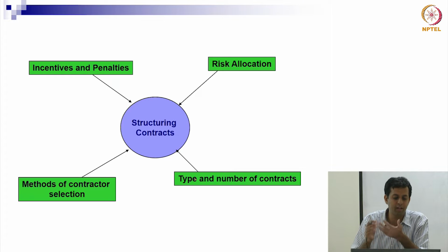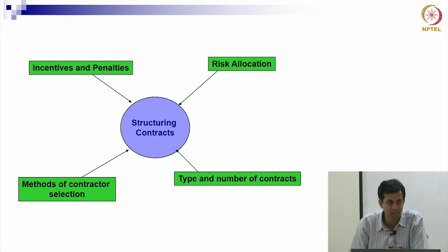There are other kinds of incentive and penalty structures which group people together, and say if something does not finish, then everyone gets penalized. On the other hand, if the entire project gets completed ahead of time, everyone gets rewarded, and so those are different kinds of incentive penalty structures. Most of you have taken a basic class on contracts. We've talked about cost plus contracts, which have a certain incentive and penalty structure, where if you have a cost overrun that is not your fault but it happens, then cost plus contracts take care of that, they allow more money to be paid. Fixed price contracts, on the other hand, penalize people if there are mistakes or if there are changes, additions, etc.